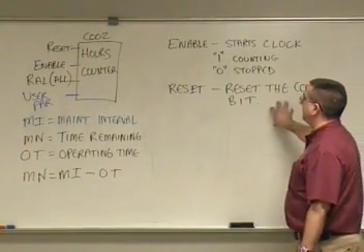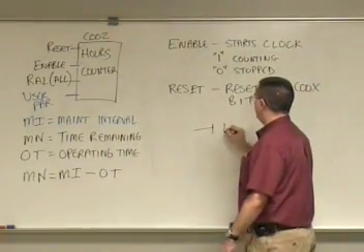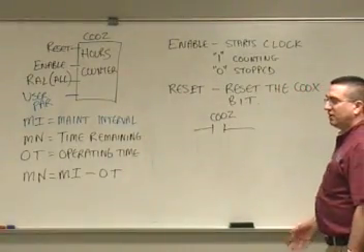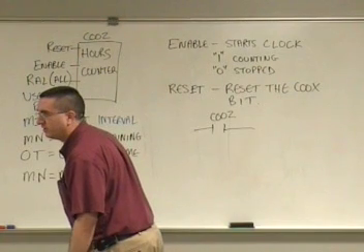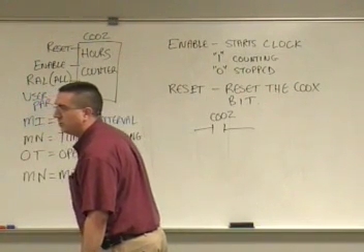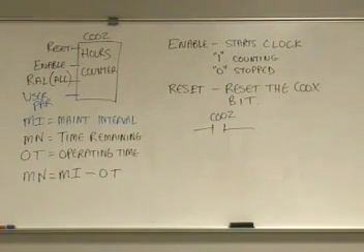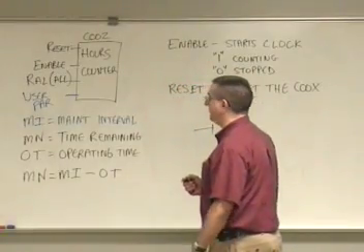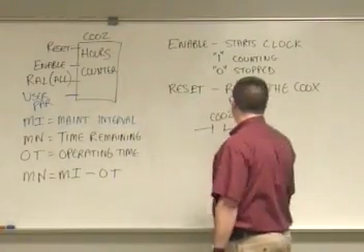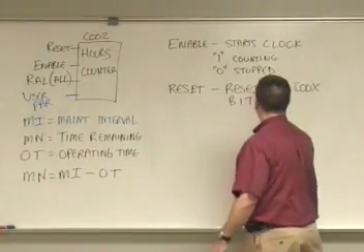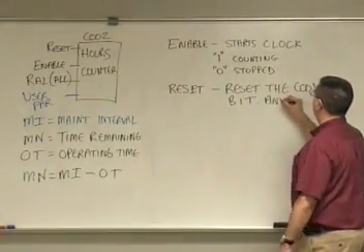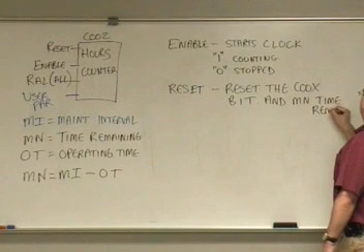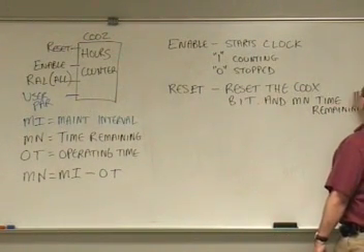Once that C002 bit turns on, I can reset that bit using the reset. Let me just make sure here. Oh, okay, and there's one other thing it resets too. It also resets the time remaining. It resets the C00 bit and the MN, which is time remaining, we talked about.